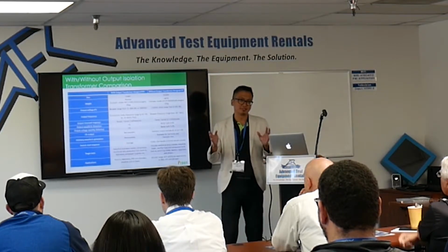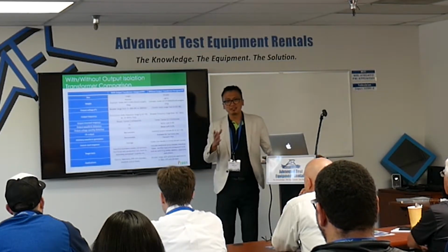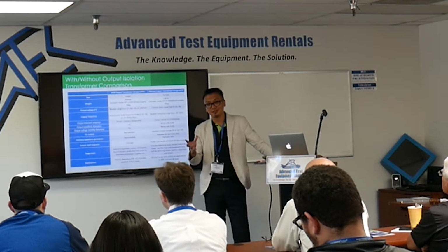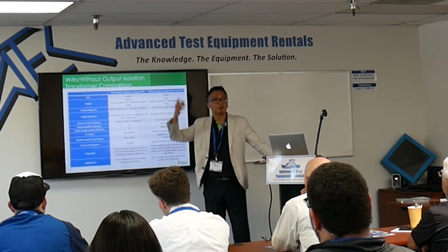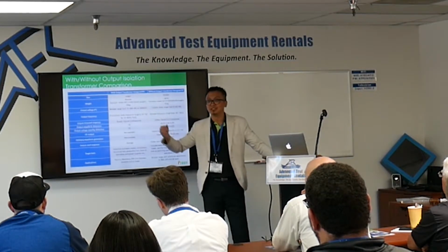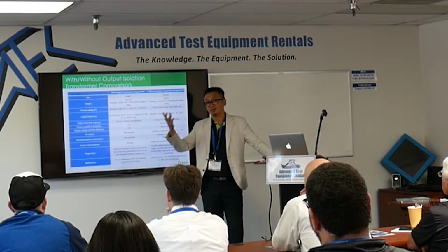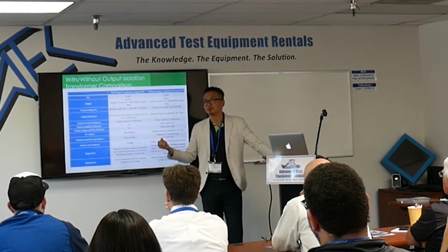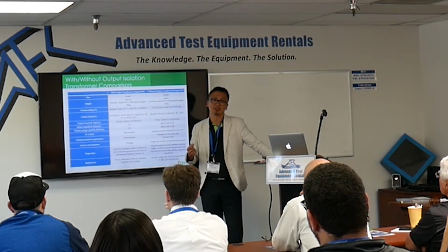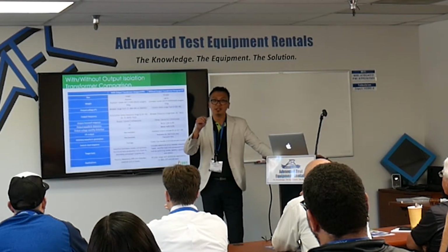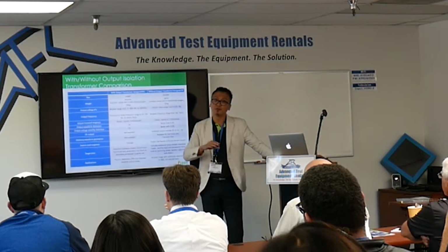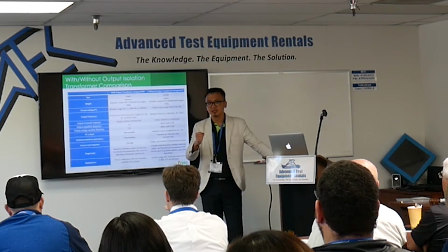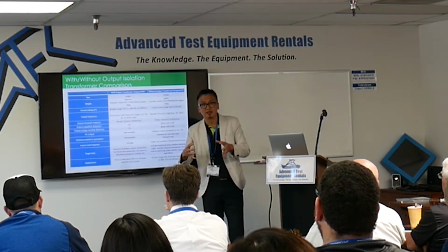Okay, let's talk about the UPS industry. When you order a UPS, from, like, everyone knows APC, Eaton, you will see they have a difference: they call it a low frequency output transformer or a high frequency output transformer. What's the difference? If you're using it for industrial purposes, you better choose a low frequency output transformer because it's more robust. And it's a real transformer there, not high frequency.